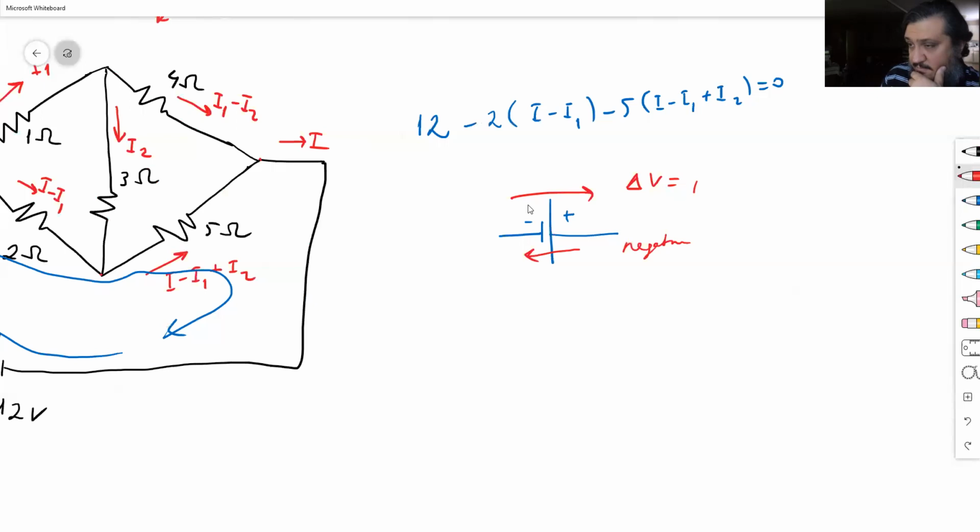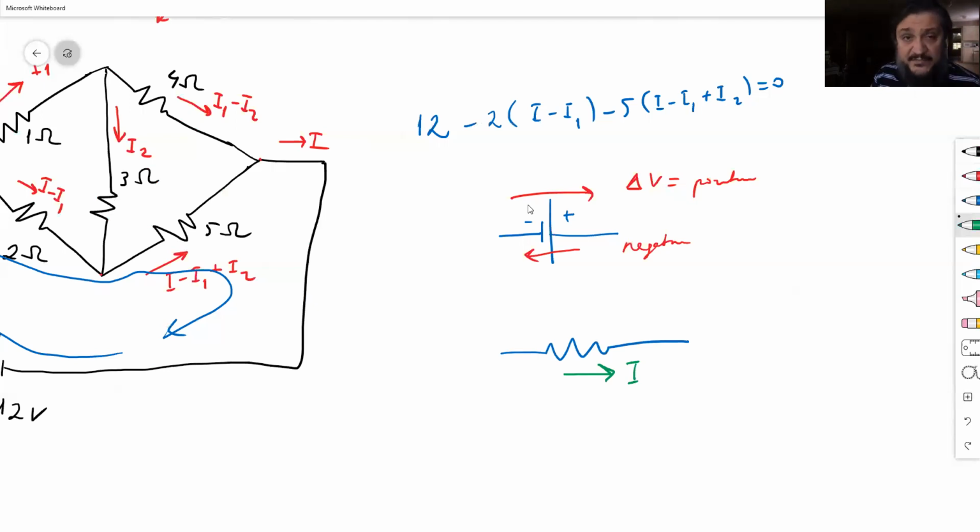Simple as that. When you're traveling through a resistor, once you decide what the direction should be, you don't change it. It's okay if it is wrong. In the end, you will find a negative number, and you know that you did wrong. Just make it positive. But once you pick a direction, just stick to it, okay?